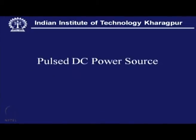So, what are those materials of immediate interest? Say for example, non-conducting material having poor conductivity, say in the ceramic group, it can be some oxide of metal, it can be some sulphide of metal, though nitrides and carbides are usually conducting, but say tungsten disulfide, molybdenum disulfide, which are of immediate interest in tribological application, or ceramic coating, which also has an interesting application in heat shielding and also in wear resistance.